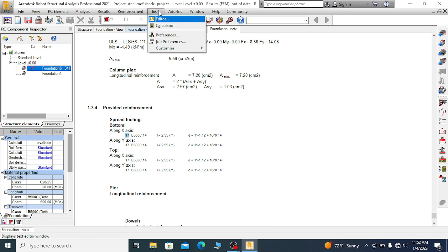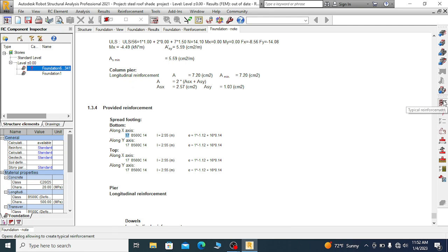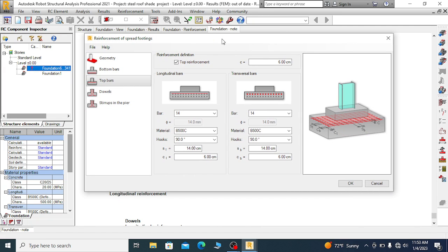Okay, here I choose, where is the calculator. Okay, now let me calculate this: 17 times 49 times 3.14, divided by 2.5, the width. So the amount of reinforcement per meter width is 1046, but here it is 559 millimeters square per meter width. So we need to increase the spacing of the reinforcement, because this will not be economic. So here the spacing has to be revised.